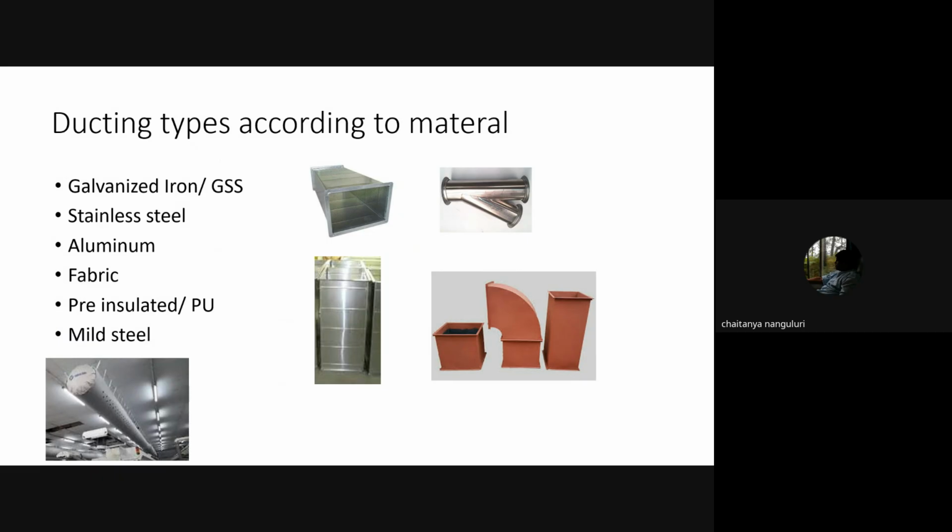When the AHU is off, it'll be almost like a flag, it will sag. But the only problem is if you have rod ends or anything, that will eat away at it. Number one, obviously your rod ends or anything can make punctures in it, right? So in the long run, it's not a solution. Number two is you can use it only for uniform distribution. And that's also if it's straight. If you have bends or anything, your static pressure also will be higher. So you have to waste a lot of energy for your fan as well.